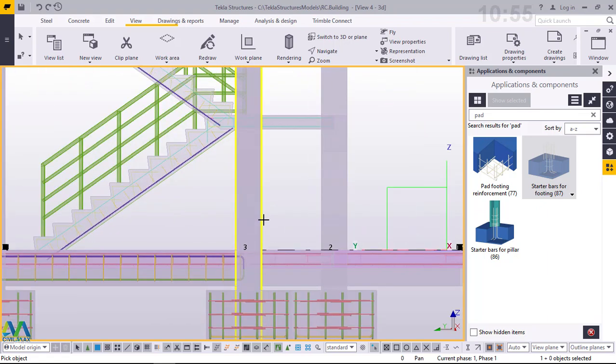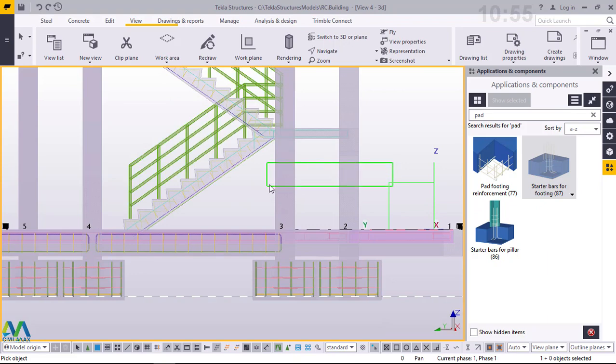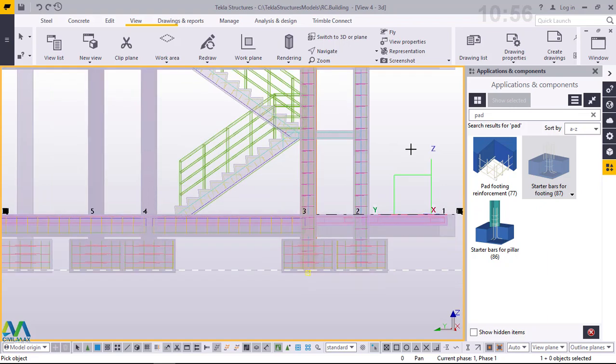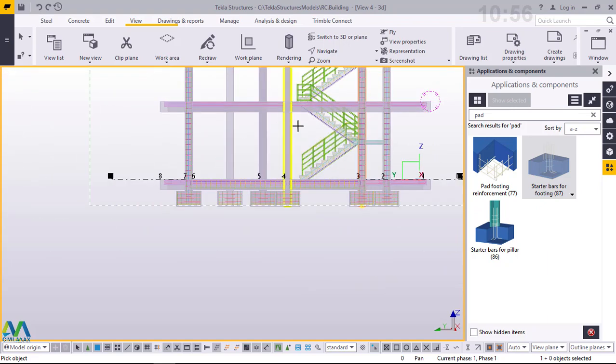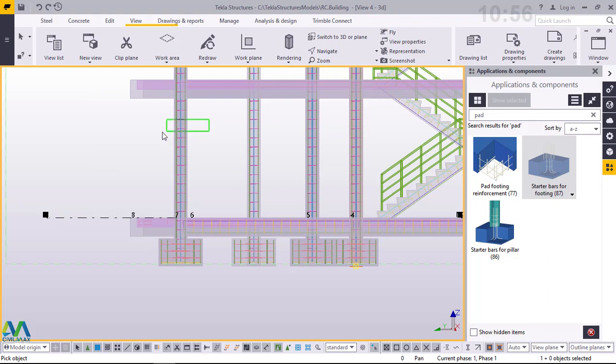having made the settings we made as a default setting for all the columns, we'll just go ahead and start selecting the columns like that, and select the columns here like that, and we'll do the same thing to columns in line with this, or columns in this line.